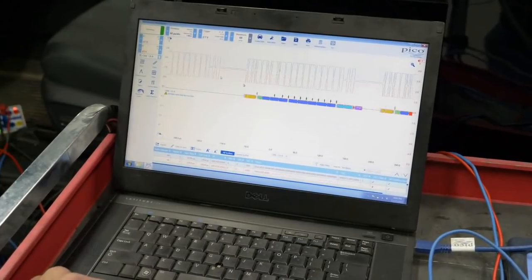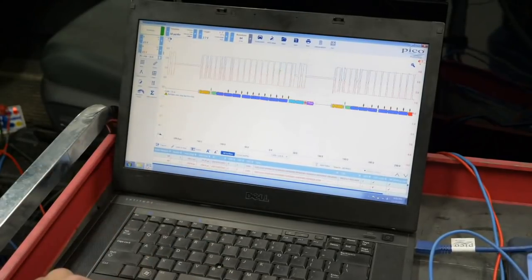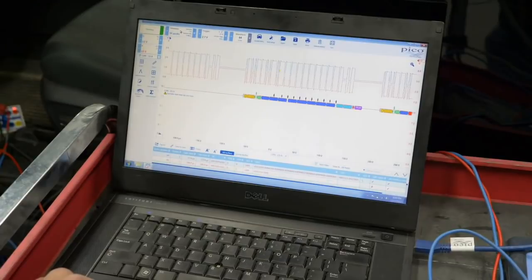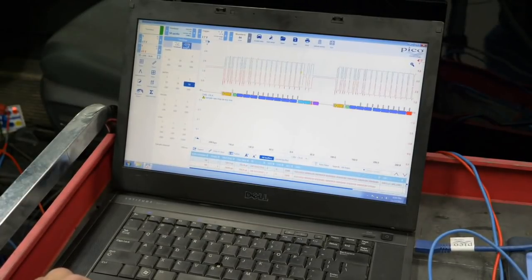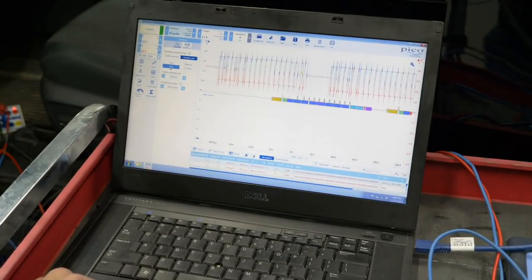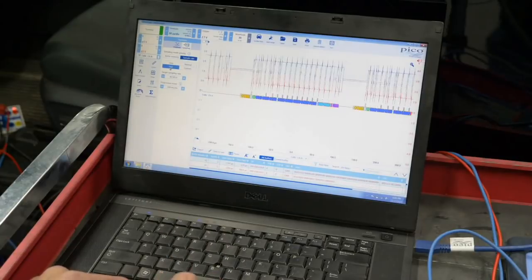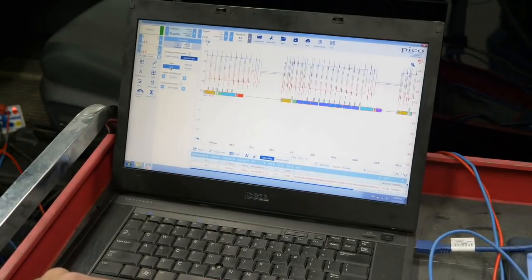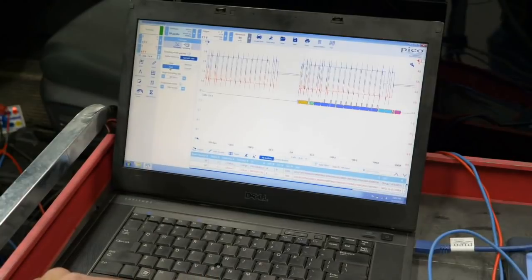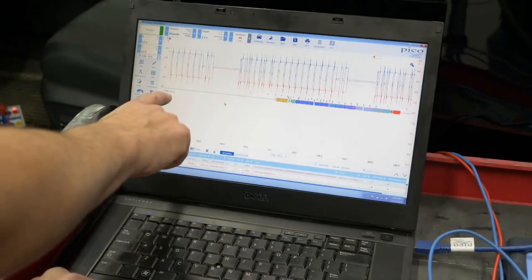It's probably correct, but I do admit I don't really want that on there. What we can do is increase the sample rate, I believe, if I go to my time base and sampling and I can go to fast, which should probably quadruple my sample rate from 20 megasamples per second. I think if it's more than 80 megasamples per second, I'm on a different technology than most automotive. So let's see if that makes it go away. It looks like it does.